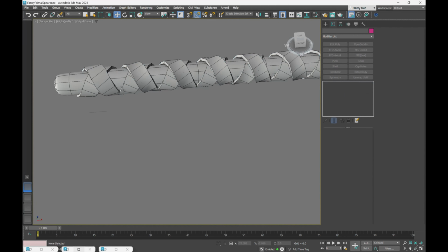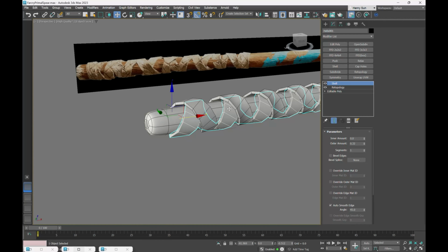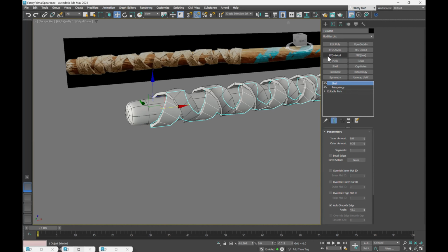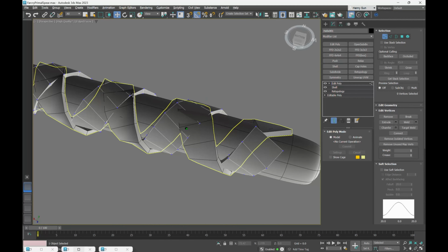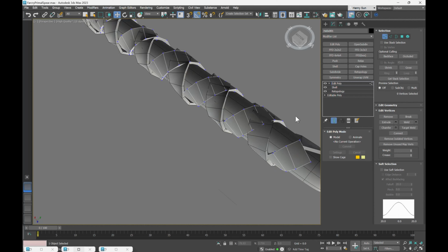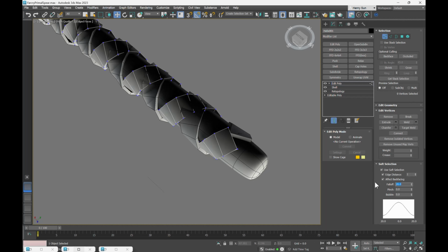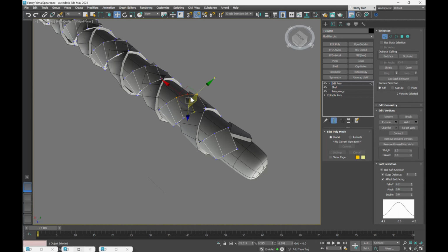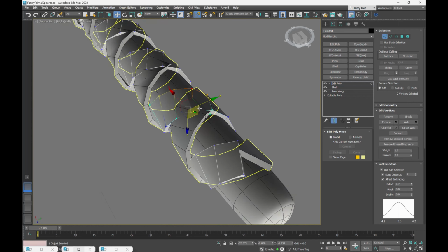Okay. And the other shape, we're going to do a very similar thing, except we're going to just adjust the bottom side here. So let's enable our soft select, our edge distance, and our fall off, which was 4.2. And let's take a look at our edge distance here. So let's increase that. So let's do something like 7 will be fine.